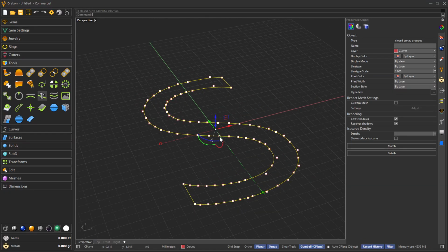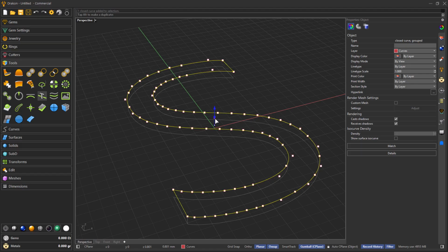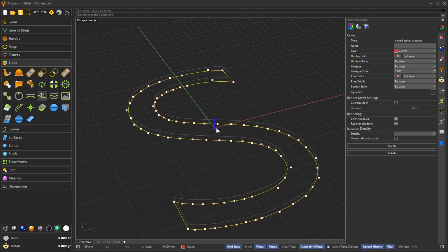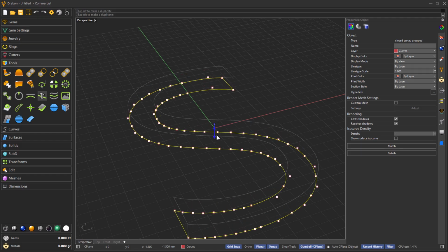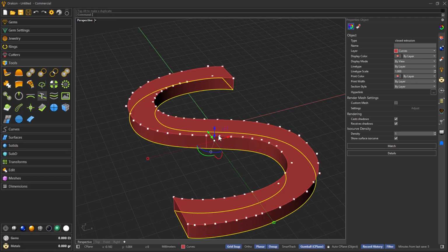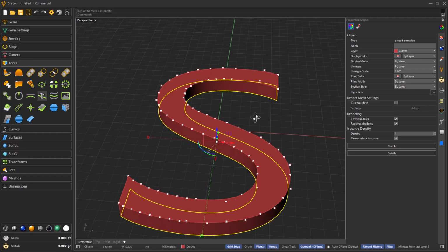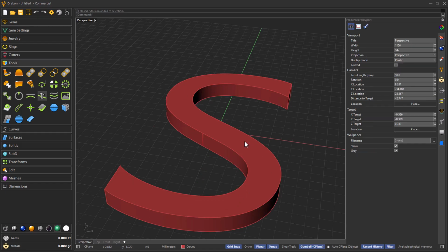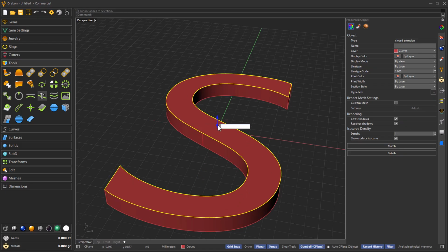Once I have my curves, I'm going to extrude. Let's say I want to enable the grid snap, so let's extrude 1, 2, 3, means 0.5 millimeters each step, so we are extruding 1.5. Remember that you can also type on the dot the distance exactly you want.